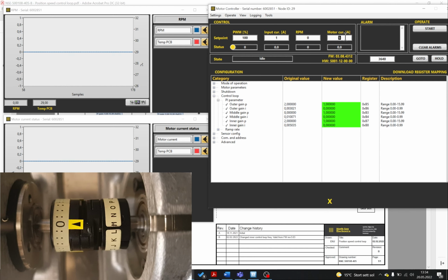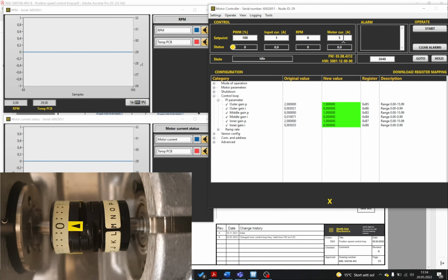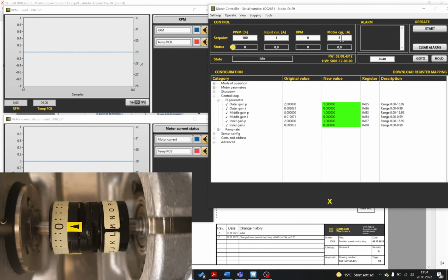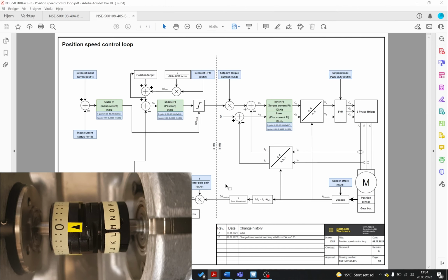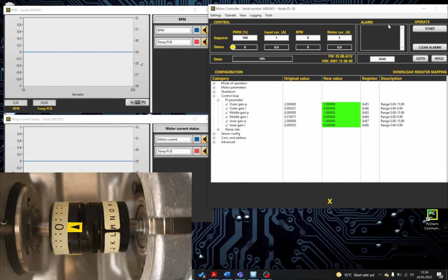So okay, I'm going to set the motor current to 5 amp. It's an okay starting point. It's a little bit more than what I expect to draw, but then I don't get any limitation on the motor current. The motor current is equivalent to the torque that the motor is providing. So it just means that we'll be allowed to go up to 5 amp. I don't expect to see that in this tuning though.